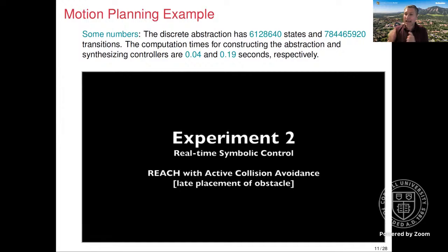Actually, you can always have this type of scenario in mind, and you can design a shield for your system. What is the role of the shield? The shield is a backup plan, a contingency plan, in case I cannot find a controller in real time, and that also limits how fast your car can drive. Because you can always rely on the shield that ensures safety of the system. You always switch to the shield. This is the bigger safety controller, which observes all the actions the other controller is sending to the system. If the domain of the controller is empty, we switch to the shield, and the shield is always guaranteed to ensure safety. For example, it might be the case that you have to brake hard because the domain of the controller to navigate the car was empty.